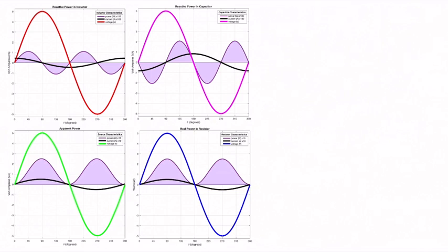If we try to solve for the power across the resistor, then we have 5 volts times the current, which we already solved before, to be 0.0500 amperes, and that is equals to 0.2500 watts. And in the figure